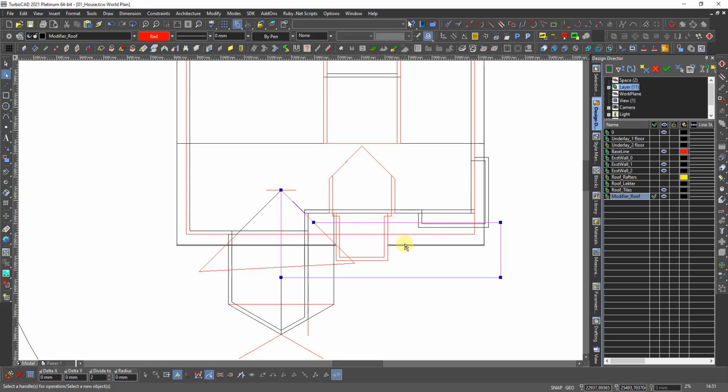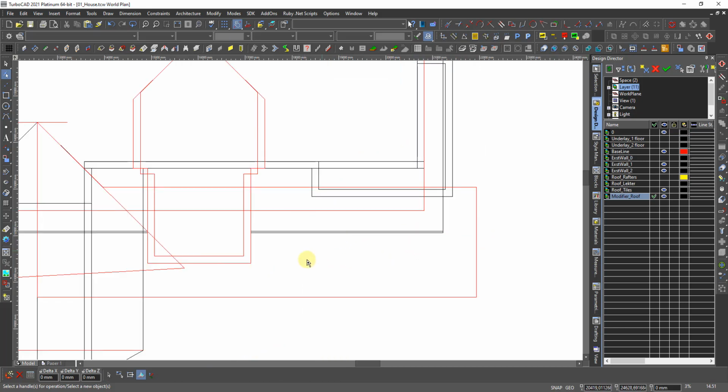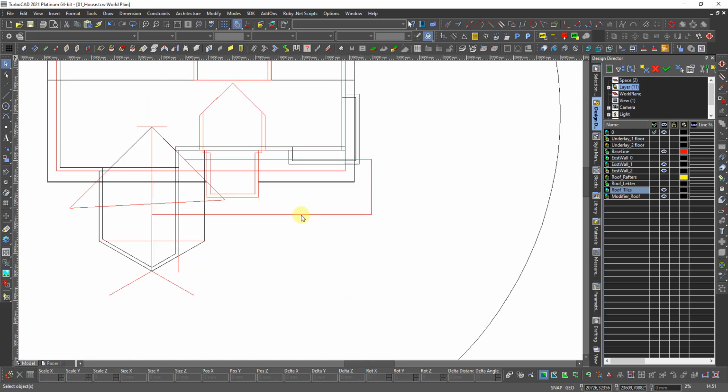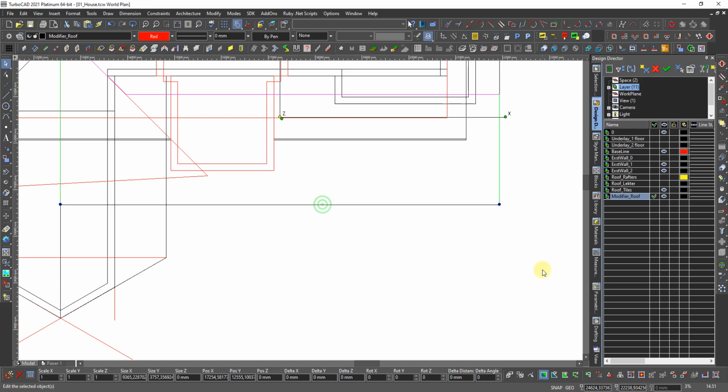So now I want to cut out from this roof this overhang also. This is roof tile, and the roof tile should be 5 centimeter more outside. Okay, forget to remember that. Then I take this, I make a copy in delta y minus 50. Then I remember to take away that. So this is the one for the roof tiles.